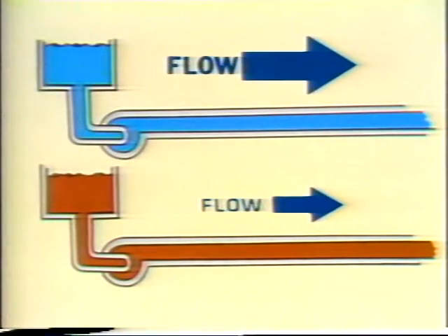Now, the negative effect of viscosity is apparent if we consider two identical pumps. One that pumps thick oil and the other that pumps water, which is much thinner by comparison. If all other factors are equal, the flow rate for water will be much higher because the water has less internal resistance to flow. To overcome this problem, when pumping some types of oil, it's sometimes necessary to heat the oil in order to lower its viscosity.